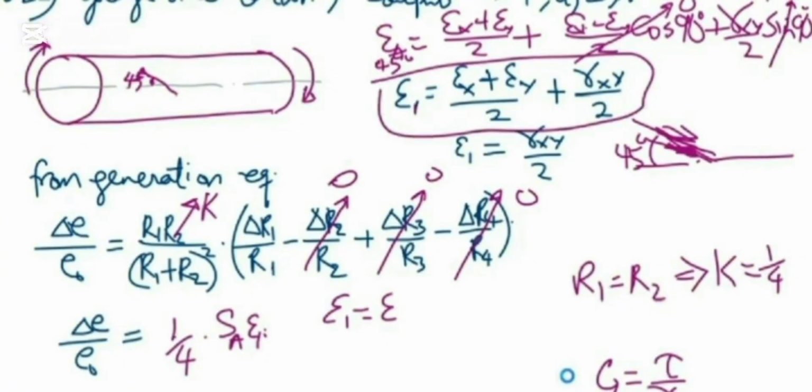So this is the only equation we are going to have, right? If we want to determine the complex strains, remember that EX and EY, do we have normal strains here? Because the loading is torsion, EX is equal to 0 and EY is equal to 0, because these are normal strains. So for pure torsion, we don't have normal strains, right? So in this case, we end up with E1 equal to what?